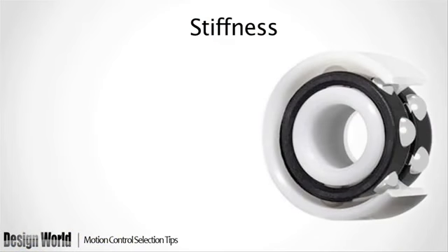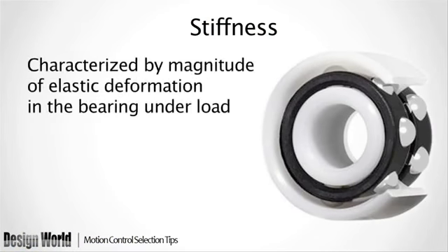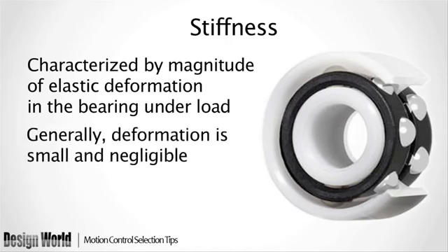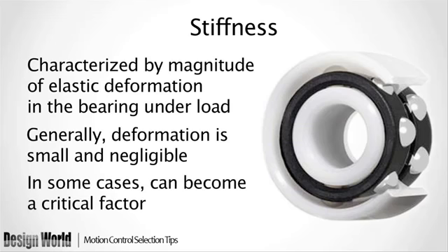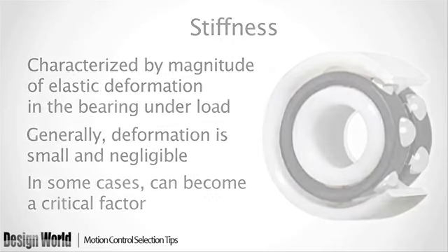Also, the stiffness of a bearing is similar to the stiffness of a spring and is characterized by the magnitude of the elastic deformation or resilience in the bearing under load. In general, this deformation is small and can be neglected. In some cases, however, stiffness becomes a critical factor. In general, the contact conditions between rolling elements and raceways in roller bearings provide a higher degree of stiffness compared with similarly sized ball bearings.